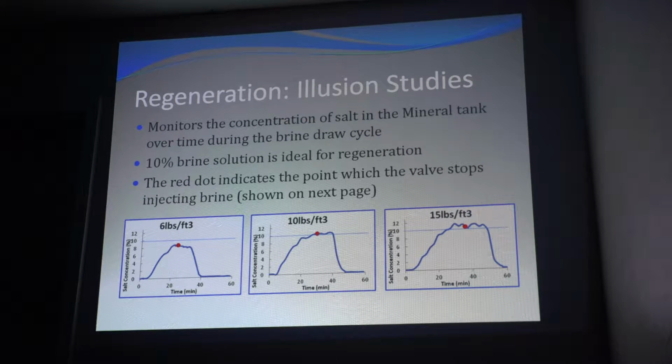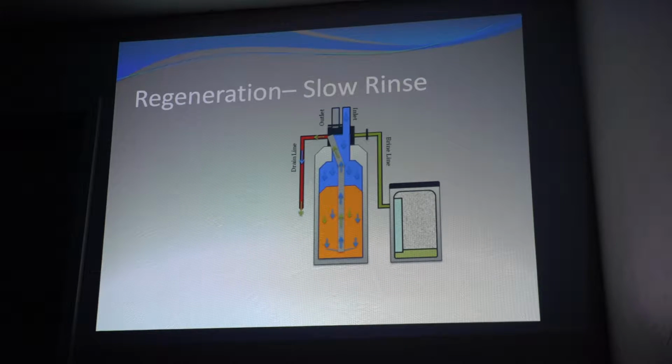That makes sense. And that's not always a bad thing because if the injector is plugged, it's been a while since they've had soft water anyway. So you're giving them a super regeneration, somewhat eliminating the need for double regeneration.